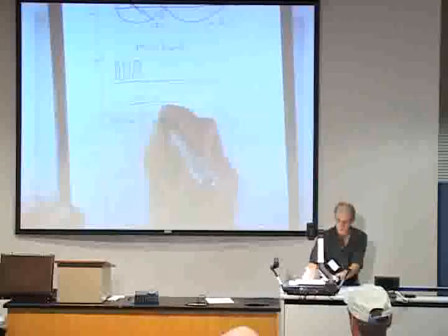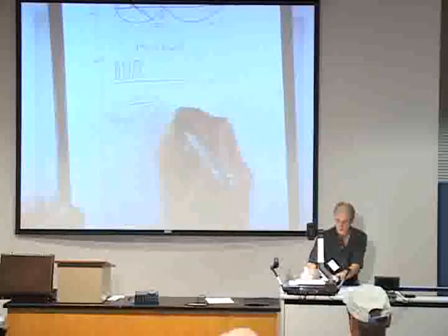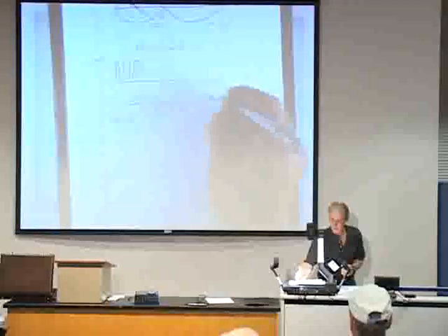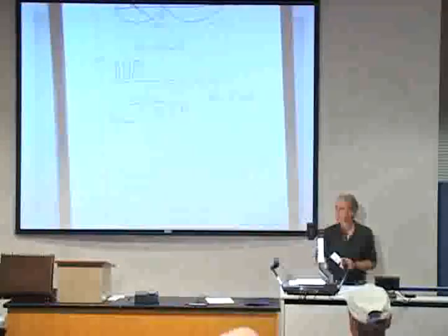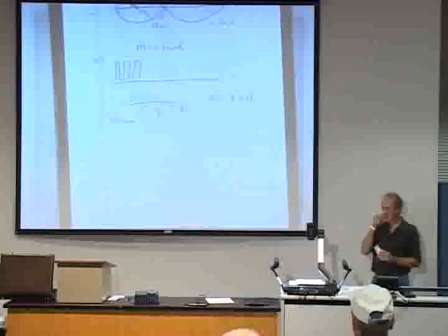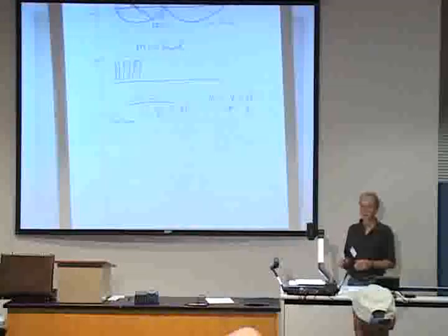And that's going to be equal to the resistance of the wire times the amps, how many amps you're running down that wire. And so when you're choosing wire and sizing wire, if you have a lot of amps, wire size is built around the number of amps on the wire, and power is watts equals volts times amps. Little basic electricity. So if you can up your voltage, if the voltage goes up and the amps come down, you can use smaller wire.